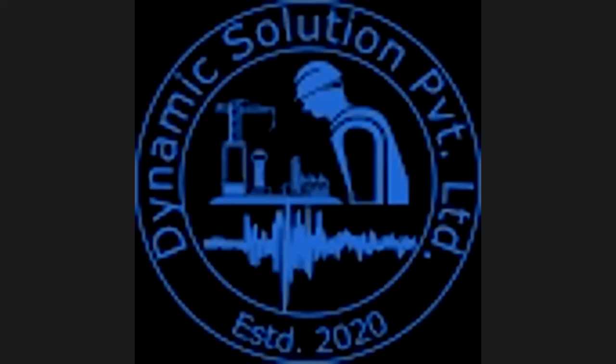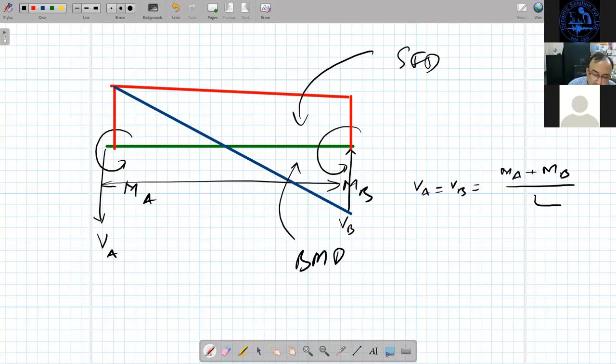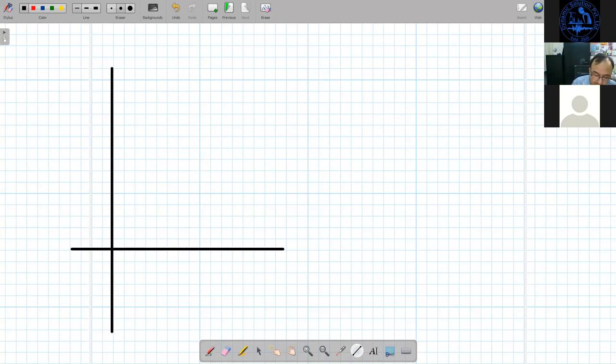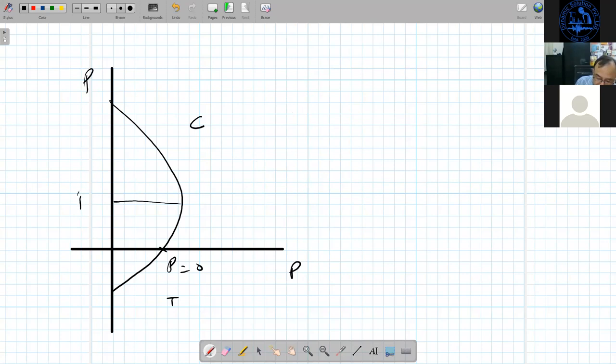So let me explain this. Again, I will share my screen. All right. So PM interaction curve of a column is like this. Okay. This is P equal to 0. Means here the column is acting like a beam. Here it is tension, here it is compression, and somewhere here it is the balance failure.